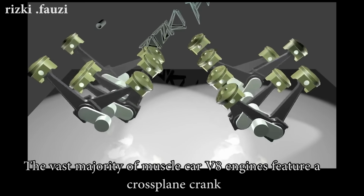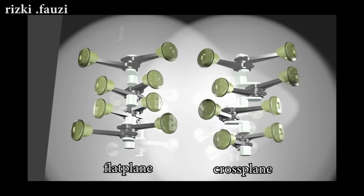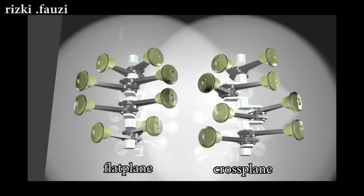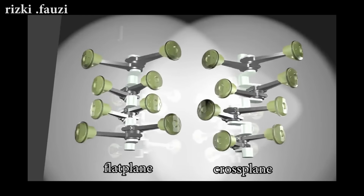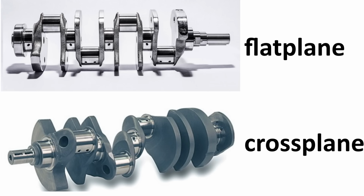And the cross-plane crankshaft means that there's a cylinder firing more often when compared to a flat-plane crankshaft. And this is good because it creates a smoother running engine and a better balance between the two banks of the V8 engine. But typically, cross-plane crankshafts are bulkier and heavier when compared to flat-planes, and this makes them less suited for high RPM operation.